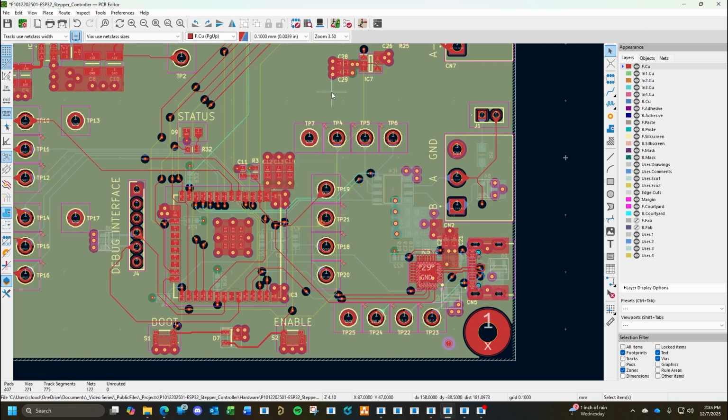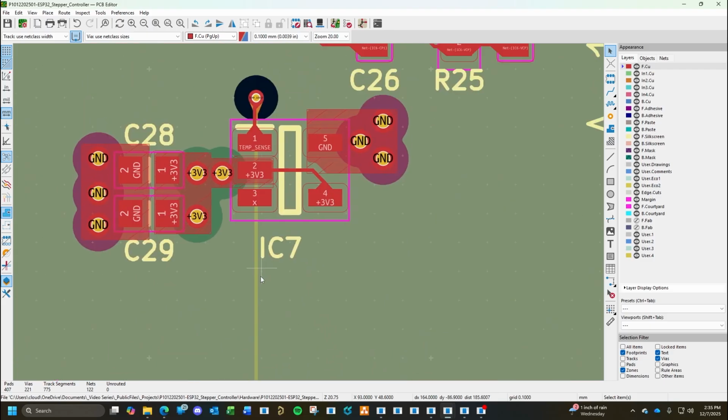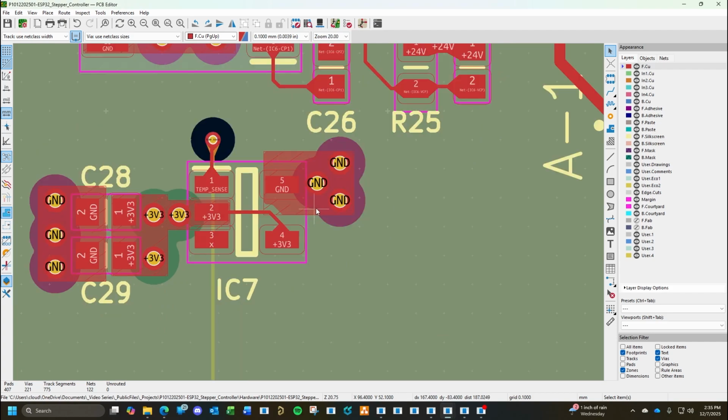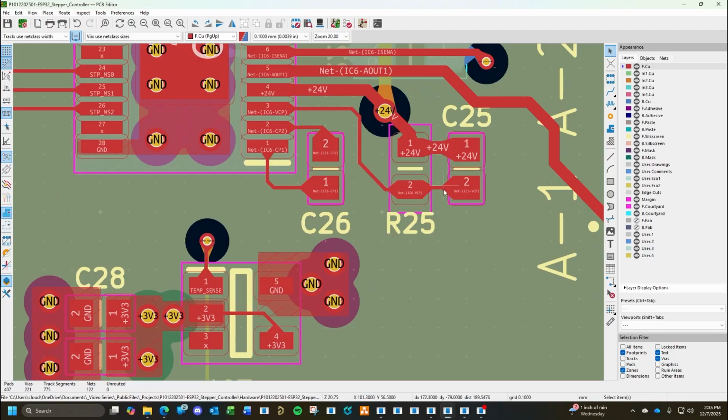Repour anything. Okay. So teardrop. Basically, it bolsters your connection to a pad or a via. I mean, other than the big zone pour like this, but if you notice, we've had our traces, and now instead of just going in here, we've got this.